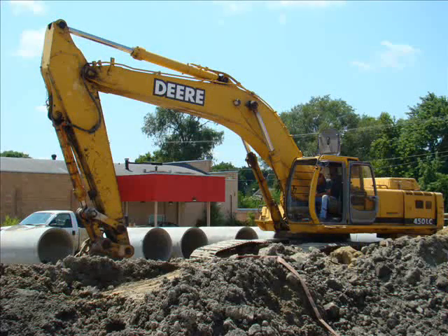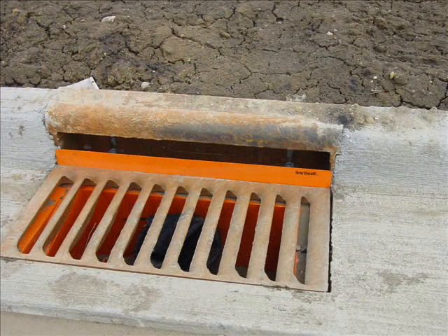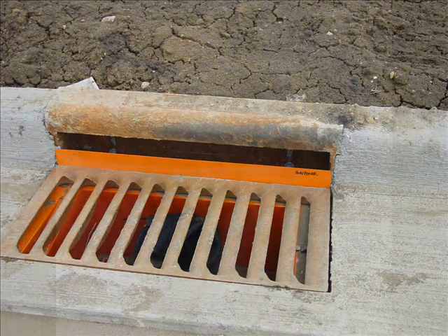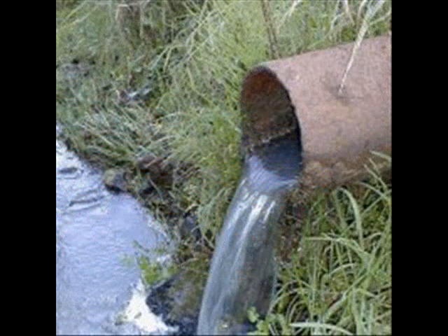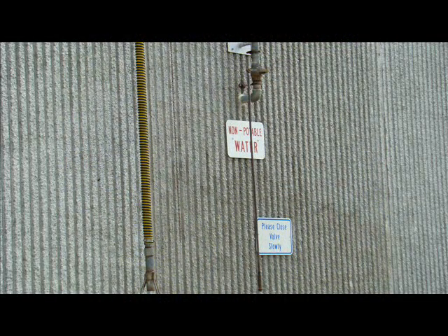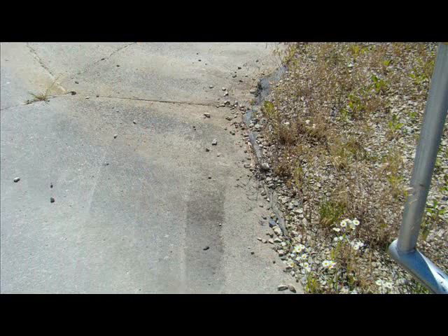Do you have any active construction? Are necessary erosion, sediment, and velocity controls in place? And finally, inspect outfalls to look for the presence of any pollution coming from the facility and any damage to structures. Look for evidence of spills, leaks, and also look for cracks and other degradation of structures.